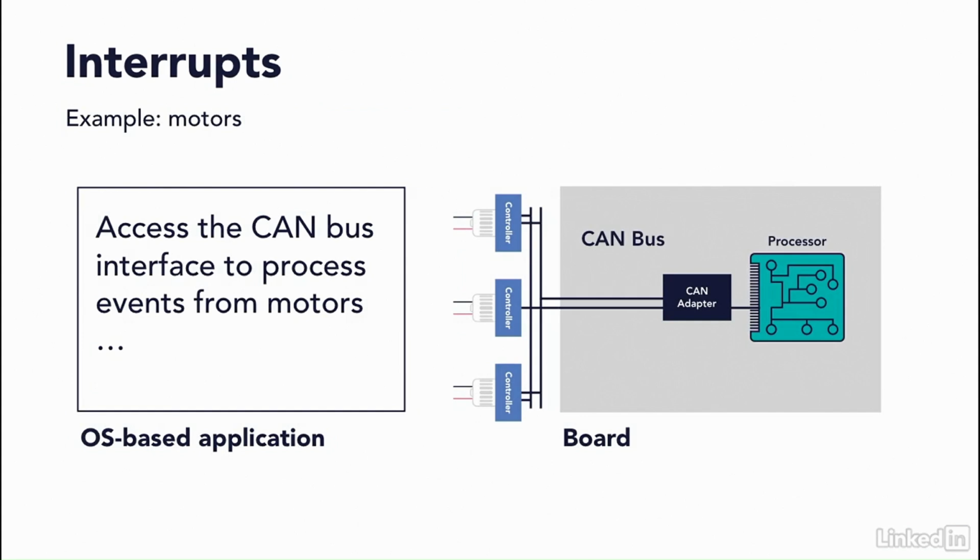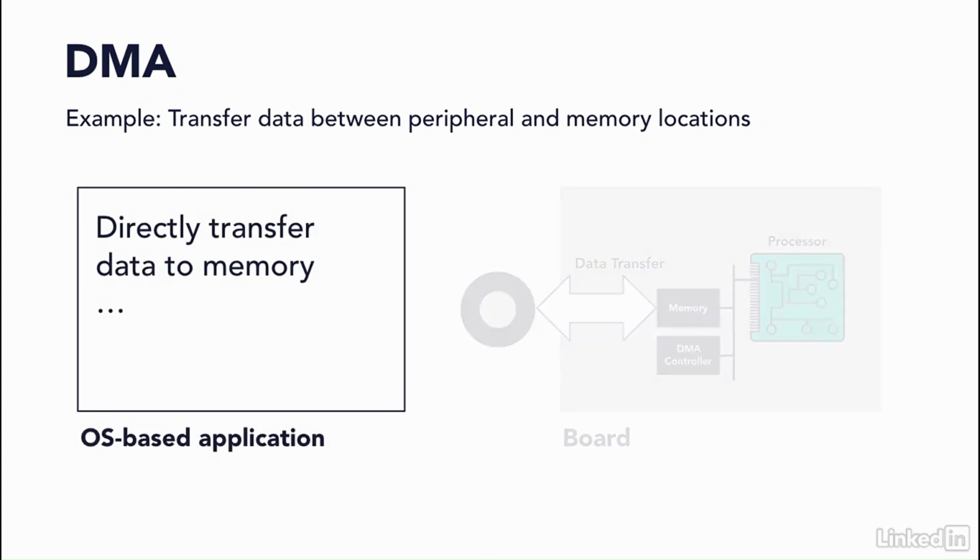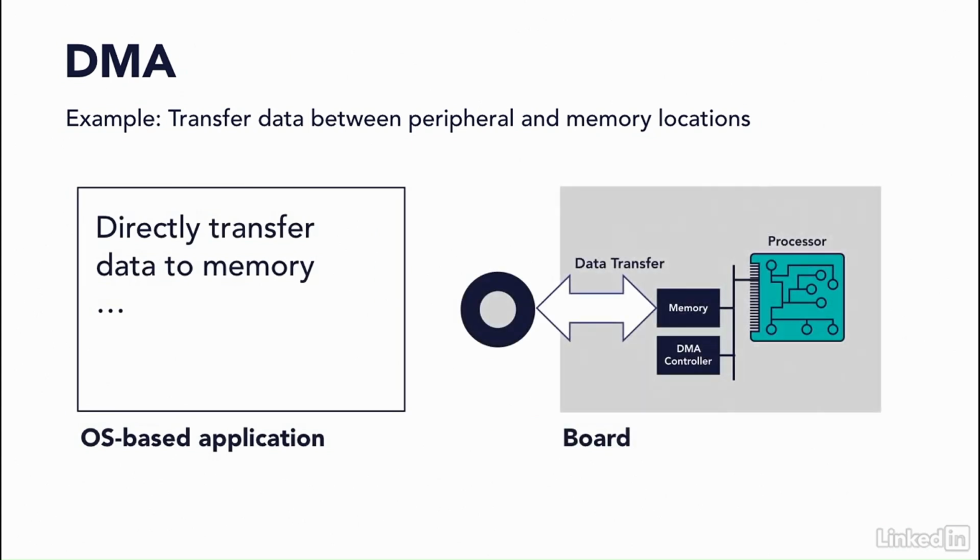Some sensing devices need a bus interface to communicate with OS applications. For example, for an OS-based application with a CAN bus driver for the CAN controller module used, you can connect the CAN bus controller and the CAN bus transceiver to read many sensors in a vehicle, such as engine temperature, speed, steering, etc. Besides the GPIO and interrupts, an OS may also provide software interfaces for facilitating direct memory access, called DMA.